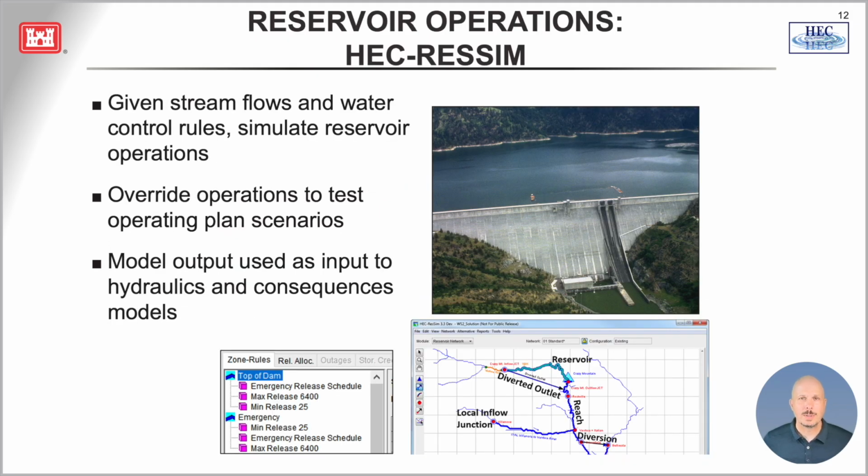The reservoir system simulation component of SWMS is HEC-ResSim. HEC-ResSim takes input flow data, reservoir operating rules, and user-specified releases to simulate reservoir system operations. The local flows from HEC-HMS and reservoir releases from HEC-ResSim feed the hydraulics model, HEC-RAS.